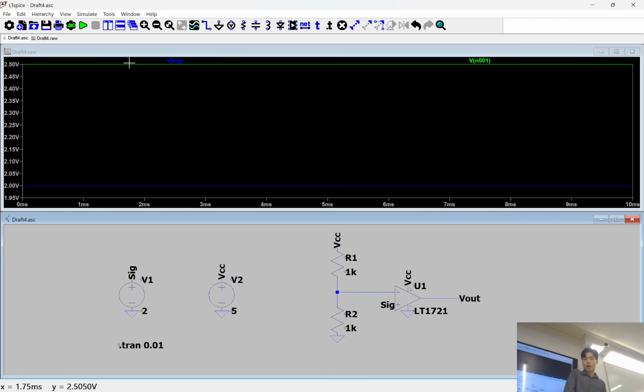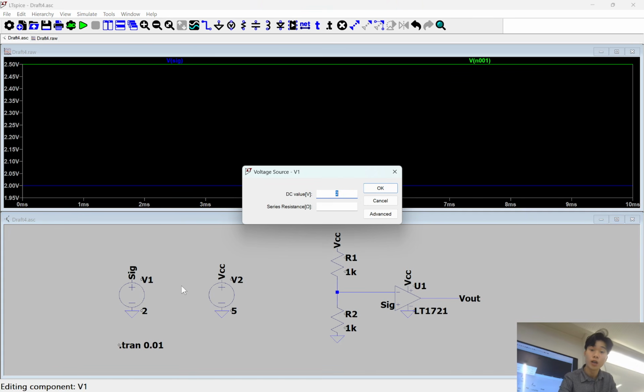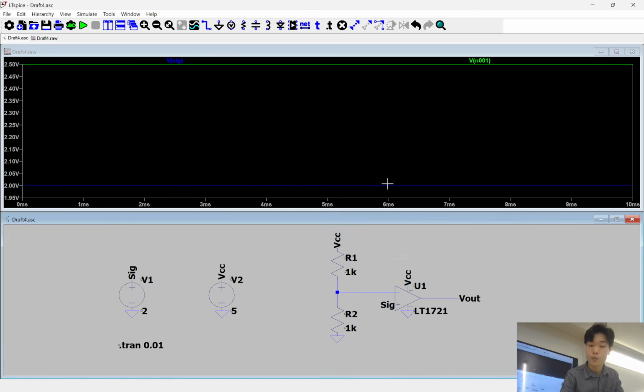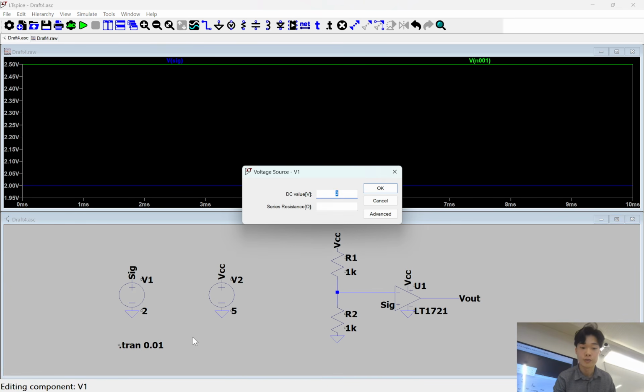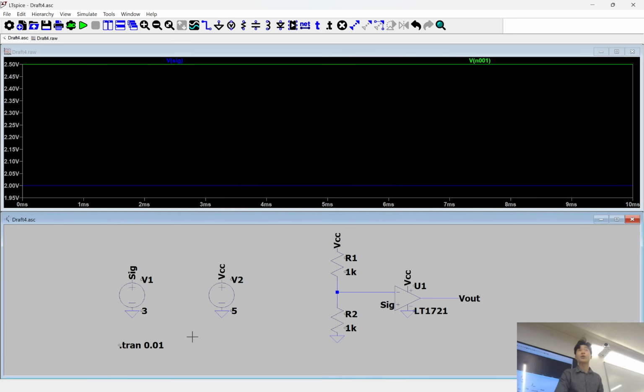Something I might demonstrate actually. So, well, we'll try a few different values. Our point of comparison is 2.5 volts. So I'm going to try different values. So let's say I have an input that's greater than 2.5. Well, now V positive minus V negative is positive. And a positive value multiplied by a very large gain from the op-amp is also going to give me the most positive, well, the largest value output.